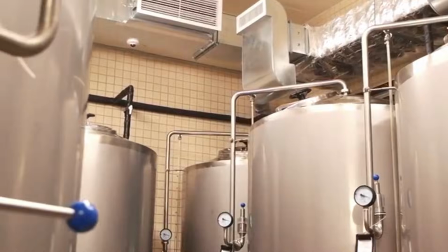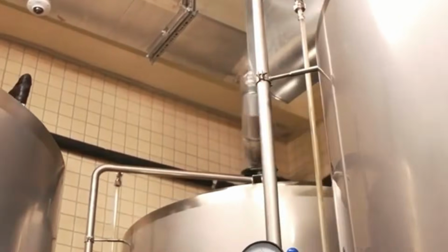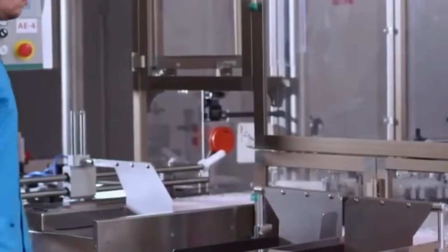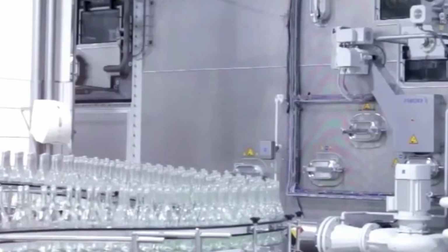Systems. High-speed cameras check for correct fill levels, proper capping, and label placement. Infrared sensors detect internal pressure by analyzing surface deformation. Some containers are automatically diverted for destructive testing, including carbonation loss, torque verification, and microbiological sampling.